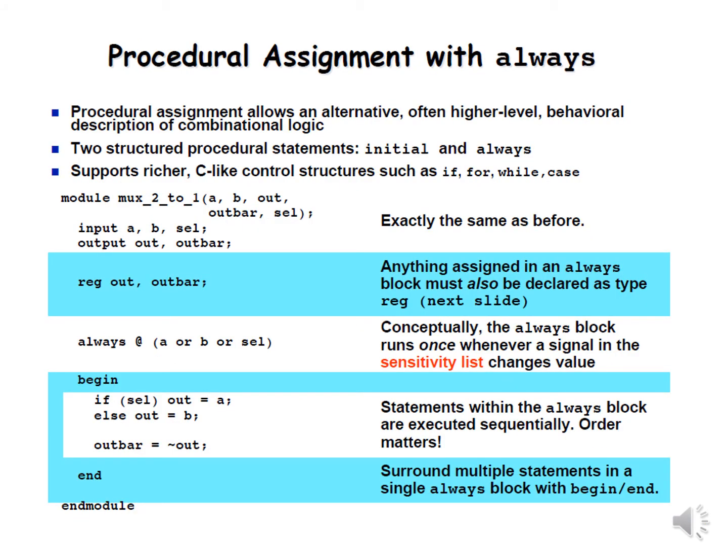And now we'll look at the procedural assignment, different from continuous assignment. For the procedural assignment, we use the always statement. Procedural assignment allows the sequential execution of the lines. There's some order. Actually, the order may matter. So it is different from the continuous assignment.